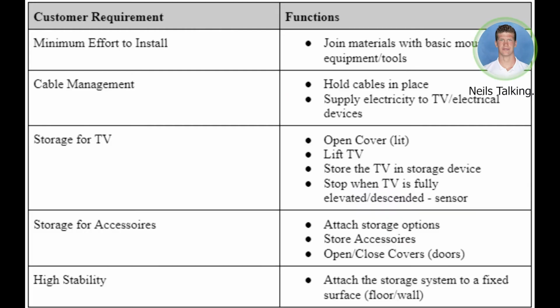The next phase of the design process is the conceptual design phase, in which we establish several concepts to ensure functionality and select the best concept for our product. First, we perform a functional decomposition where customer requirements determine the functions of the product. Then we will start the concept variant generation. In this table, we can see the customer requirements on the right side, and on the left side, we can see the functions, including the flow of material, energy, and information.